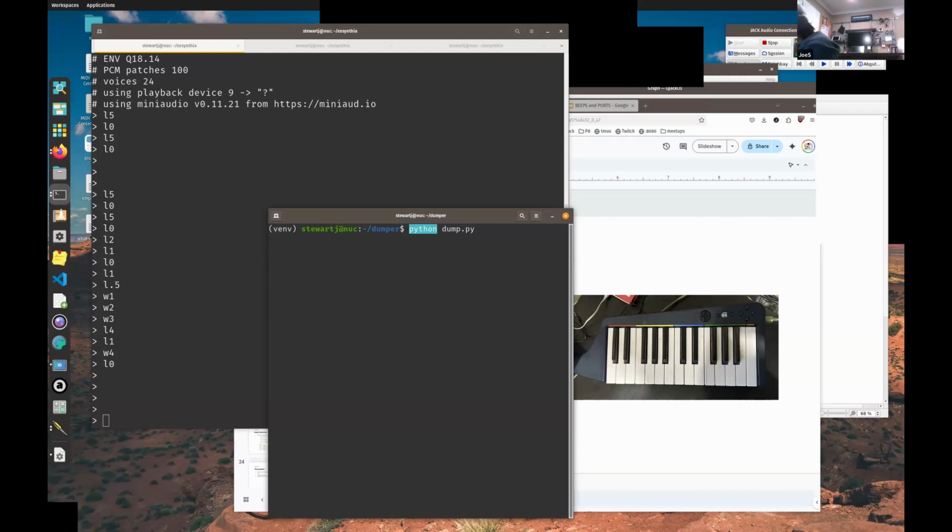Off to the side, I'm going to power on this keytar that you're seeing in this picture, but not live on video, and show you that. Let me just skip down here. I'm hitting the C key, and when I press the key down, you'll see that I'm decoding some of the MIDI stream here. That's a note on for MIDI channel 0 of key 60, and there's a velocity value. I'm holding down the key right now, and when I let up on it, you'll see that I get a note off message for the same key with a velocity associated with it.